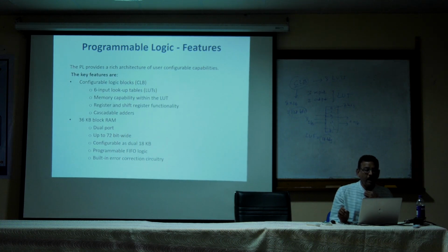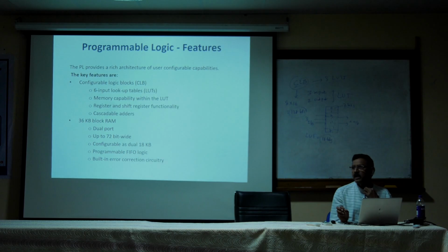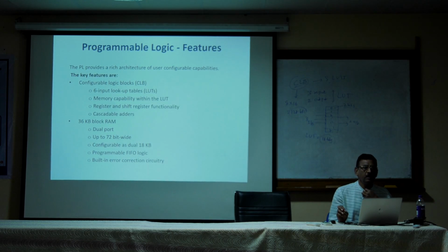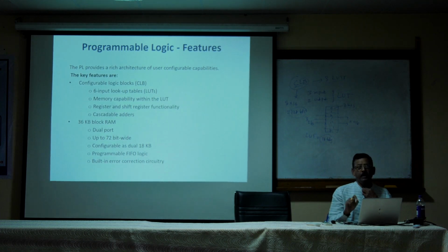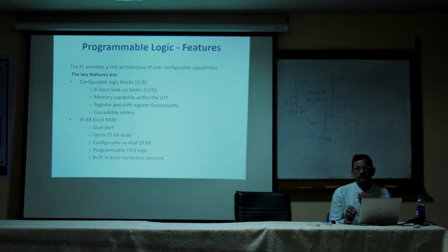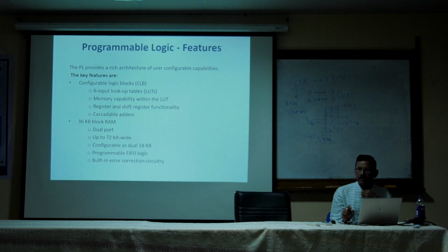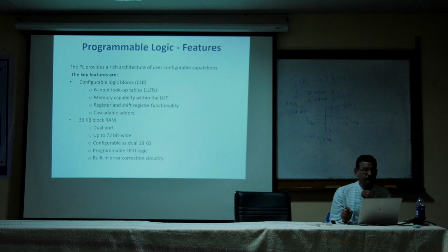And cascadable adders. So, for example, ripple carry adder type of adder, suppose if you want to implement 32-bit adder, 64-bit adder, that cascading type logic is automatically cascaded. Cascadable adders also we can create with the help of the LUTs.